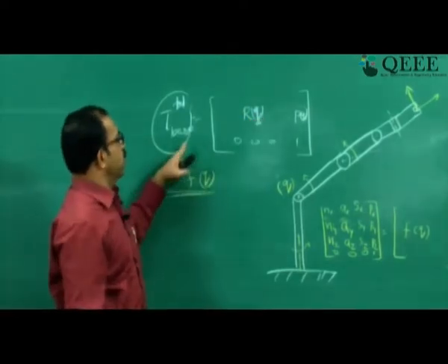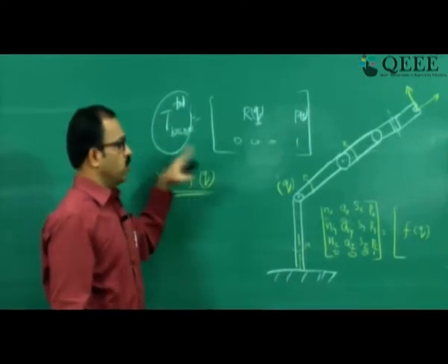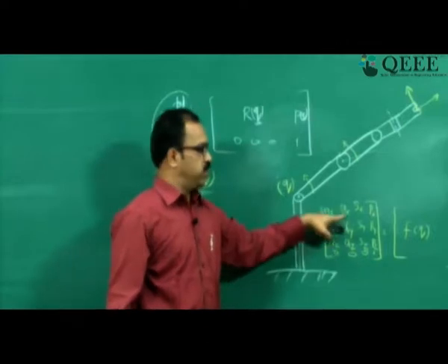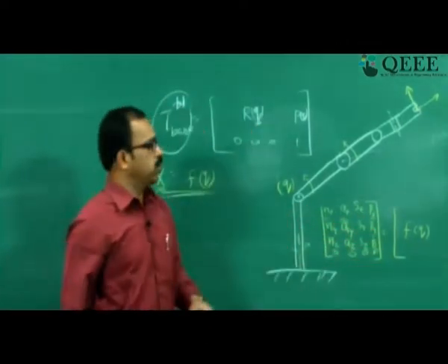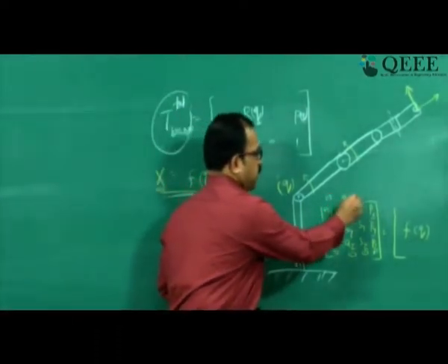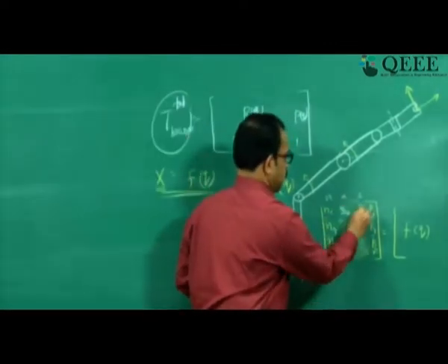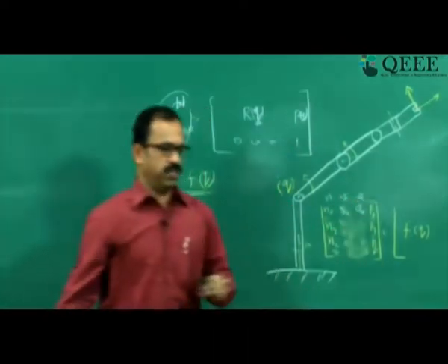In general, from Q we get the tool to base relationship. The tool to base relationship is always given as Px, Py, Pz as the position of the tool tip, and the normal vector, sliding vector and approach vector, NSA, as the orientation.